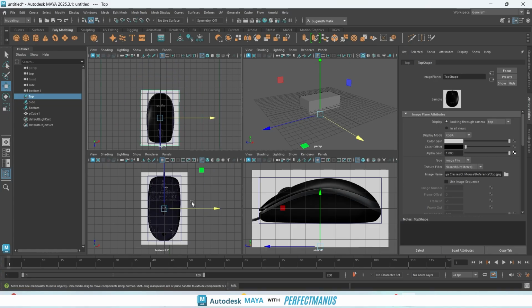See, just remember that from all viewports your images want to be 100% aligned, and these images are taken by a perspective view, a camera which has some focal length, and we don't know right now at what focal length it has. So also while we will be modeling it, your model won't exactly match your reference from every side, so you have to consider that also.